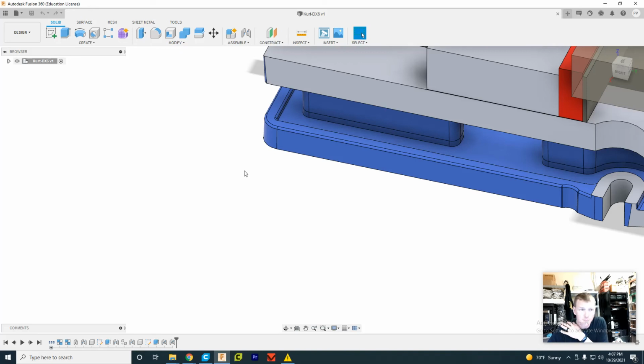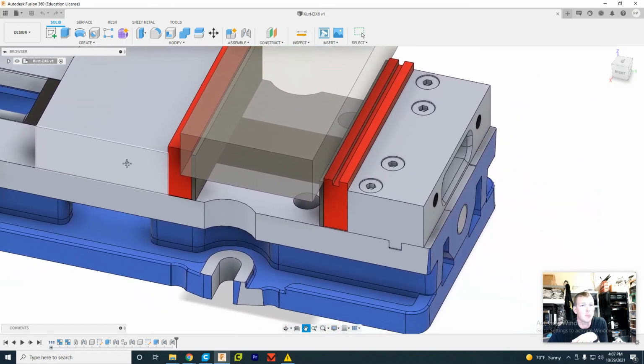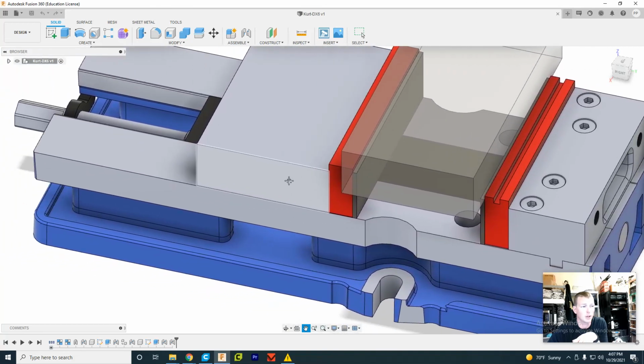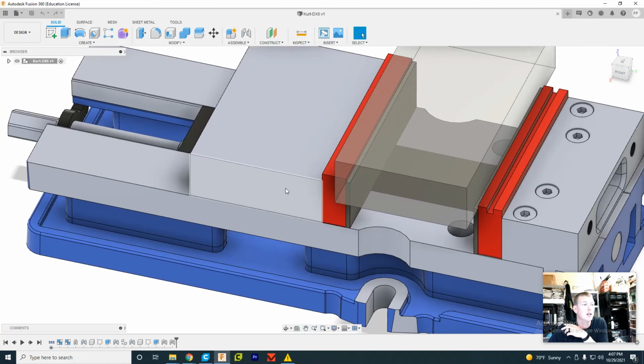So I'm going to go up here and hover over top of my part, and then I'm going to hold down the middle mouse, the wheel. I'm going to click it straight down as if it were a button. And while I hold it, I'll move this, and that lets me pan my view, so I can just move the view around the screen. I didn't physically move any of the parts. If I click and drag with the left button, I might actually move things inside the design. It looks like everything in this design is pretty fixed, so it's not letting me move anything.